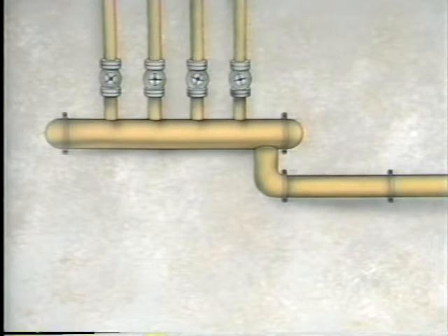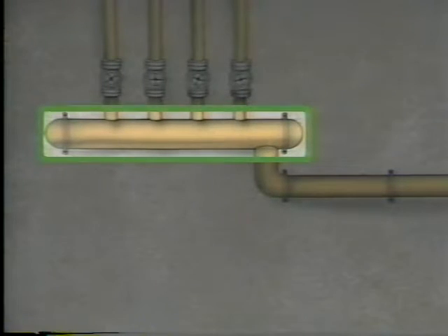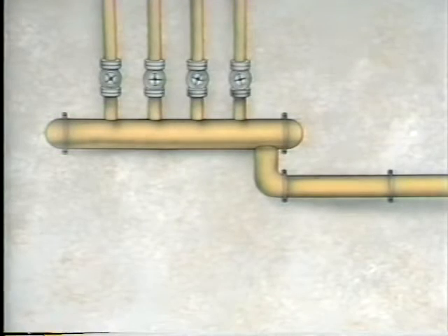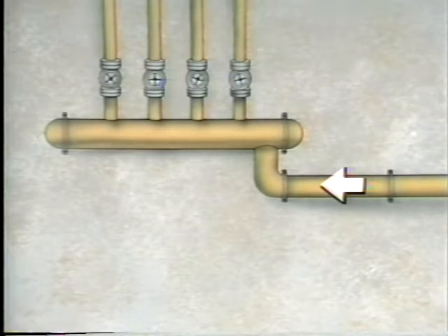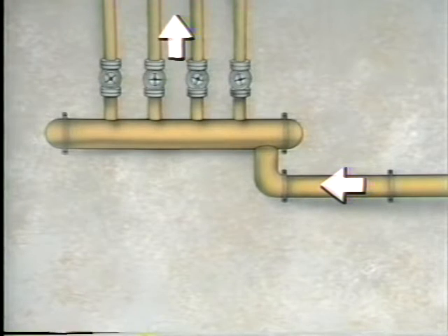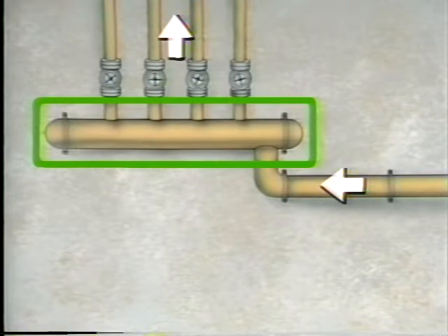The process variable that has to be maintained in this system is pressure in the header. Header pressure has to be kept at a constant value so that the flow of fuel oil from the header remains constant. As long as the amount of fuel oil supplied to the header is balanced with the demand for fuel oil from the header, the pressure in the header will not change.